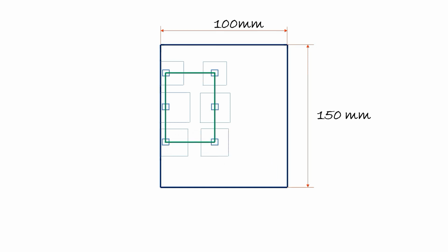Footing can't be built beyond this boundary, so the column will be positioned here at the edge of the footing, while we don't have any problem on the other side. We will design the footings in such a way that they shall, as much as possible, not overlap with one another, and shall not occupy the space of the neighborhood.